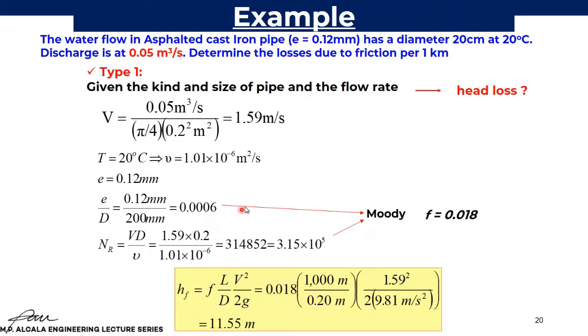Sorry about that. Solving for the Reynolds number is simply the velocity multiplied by the diameter divided by your kinematic viscosity. Another equation that can be used here is rho V D over mu, the density multiplied by the velocity multiplied by the diameter of the pipe divided by the dynamic viscosity. Okay? But in this case, we will use the kinematic viscosity.